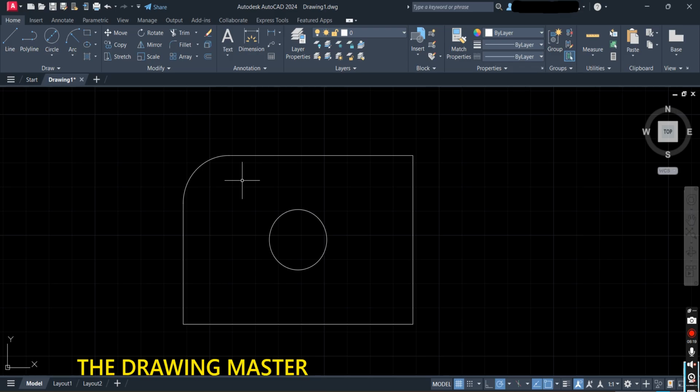So here we will discuss the fillet command now, how fillet is useful here. Instead of this, how can we use the fillet command? Now you will see that by using the fillet command it will be done within 1 minute. So choose the fillet command. It is asking to select the first object. But this is a bit of a problem here. We will not select the object. First we have to type R, enter.